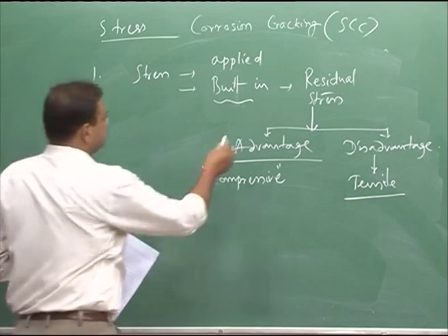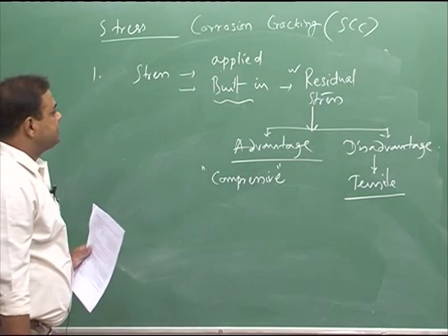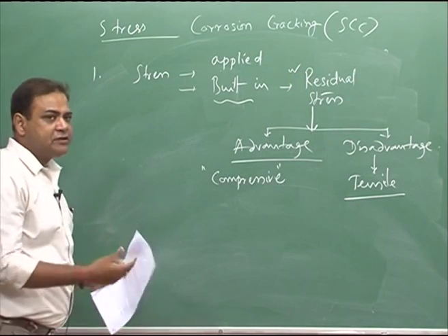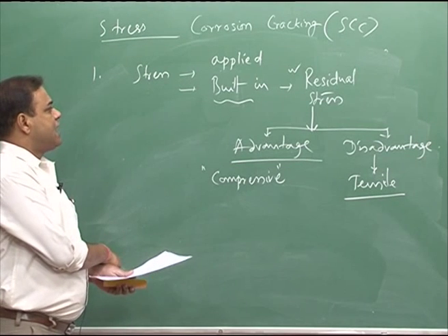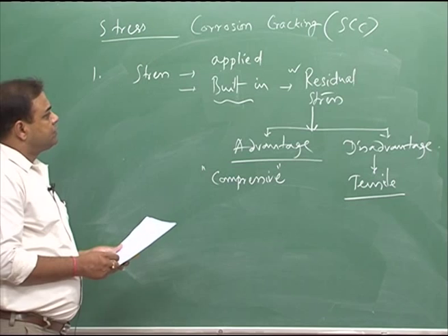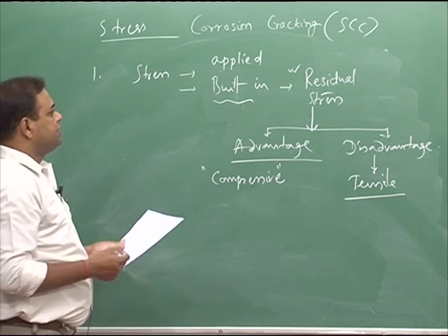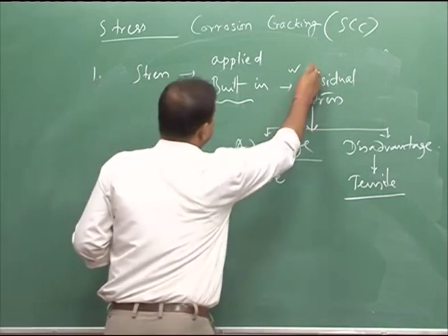So, we need to see whether the material contains a lot of residual stress, and if it does, then we need to go for some sort of annealing operation in order to remove that residual stress.